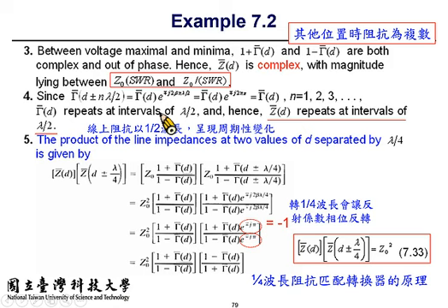So that's a very interesting property about positions on the gamma plane: for any pair of opposite positions, the product of the impedances at these two points is the same as the square of the characteristic impedance Z0.